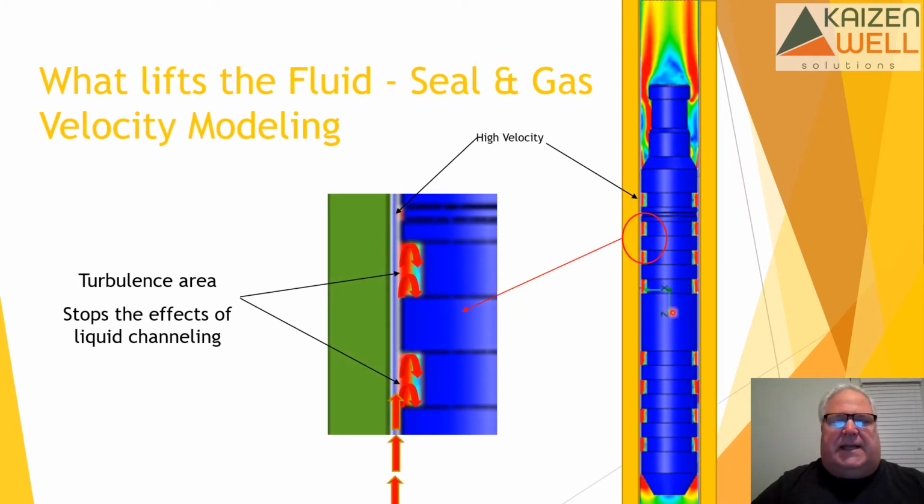So here, you've got gas breaking around the outside. And as that gas is coming around the outside, in this case, it's an example of a ring or a rib type plunger. Gas goes across these ribs, creates eddies and turbulence and stuff like that. That turbulence also helps increase the lift. Also, every one of these surface areas that there's a differential across increases that ability.